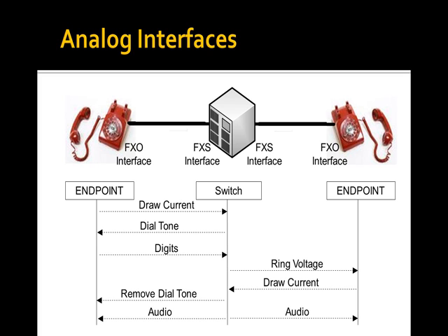Which one there? At that point, honestly, from a signaling point of view, it's arbitrary. You could pick either end to be it. The way it was done in the hierarchy is the higher level switch had the FXS interface, the lower level switch had the FXO. And if you think about it, if we tilted it so those phones were downhill from the switch here and signaling flowed downhill, then it would make sense about the orientation.